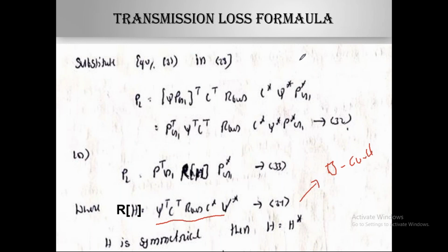We have different types of B coefficients: one is BII, BIJ, BJI, and B00. These are the different types of B coefficients we have included in the power loss equation. If you want to find the power loss equation, you need these parameters. That is the reason we are going to find all these B coefficient parameters by using equation 34.